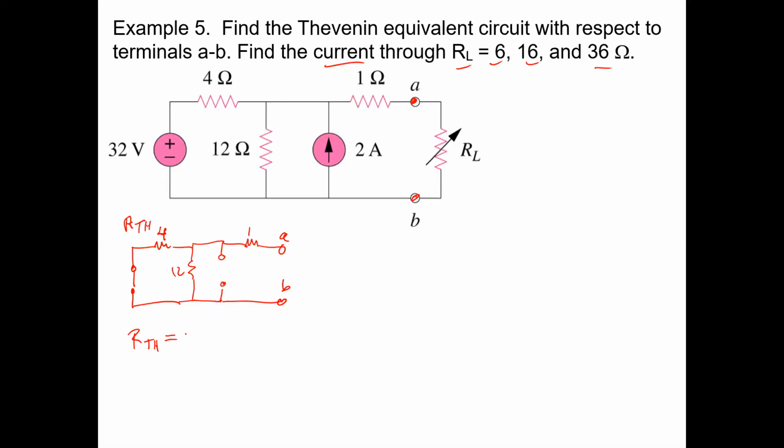Okay, Mason. What is the effective resistance at the terminals A and B? So if you hook up an ohm meter right here to that network and you're measuring ohms, how many ohms is it going to read? 4. Why 4? 4 and 12 are parallel, and that makes 3, and that's in series with a 1.